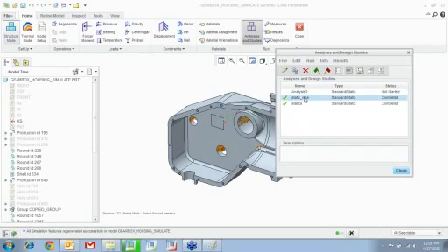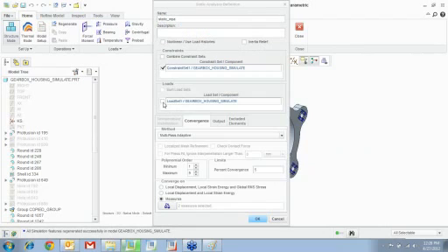Now I run a multi-pass analysis. In here, notice that I'm going to say multi-pass. My polynomial order is going from 1 to 9. All right, and you see the percentage of convergence that I'm using is 5. So here I'm actually dictating the allowable error in the model, and also I can choose what gets compared.